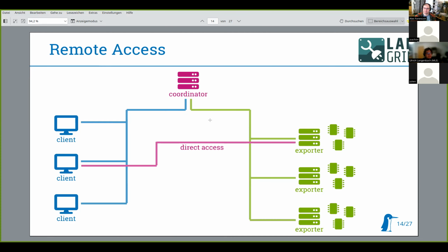And once you run this acquire process on the exporter, the hardware server gets started automatically. We have some means, at least for us, scripted into that so we can also run different versions of hardware server. So it's not the global hardware server. Yeah, because I've had issues where you've got to match the Vivado version, so depending on what version you're running, you've got to run the same hardware server version. And then I guess Intel also has their JTAG daemon, which is a similar idea. Yeah, we made this work as well. So currently we are able to run similar things for Intel and Xilinx devices. We are still working on Microchip support, and we haven't looked at Lattice yet. But I guess for you that's not a problem.